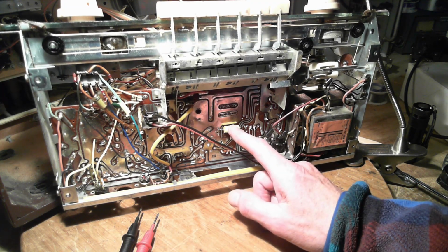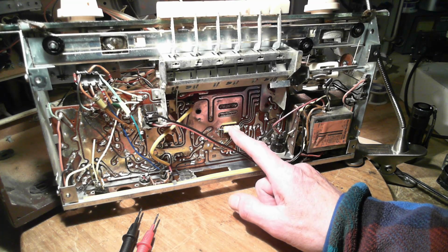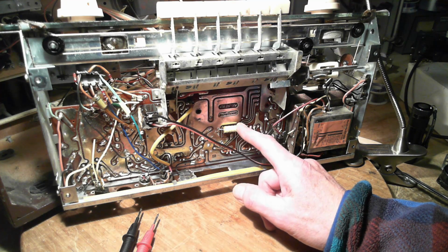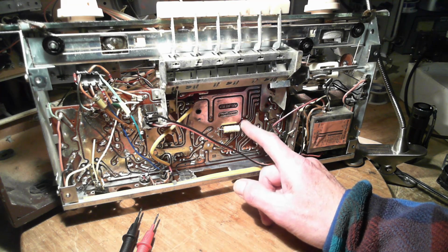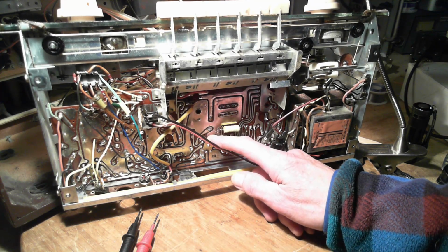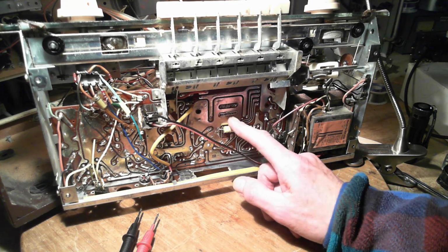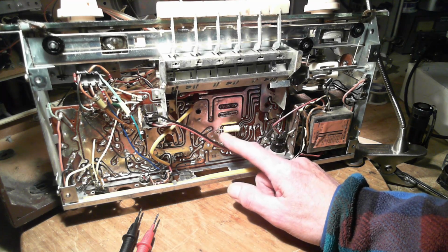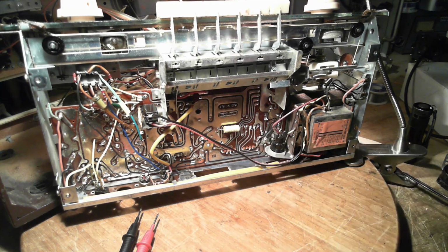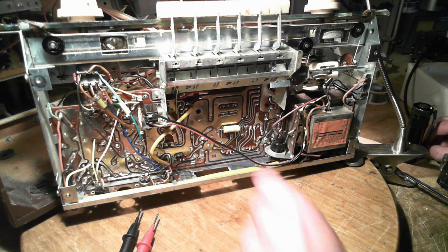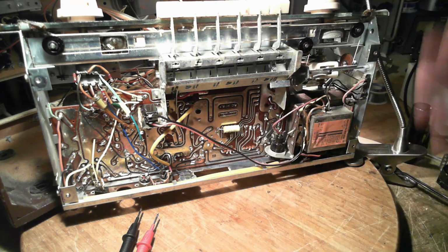The solution could be just turn this capacitor right around. Just turn it around, put it back in, and if my theory's correct, that would move the outside foil connection over to here on the ground, and so the outside foil would be grounded, and that would shield the capacitor from whatever's going on in this zigzaggy piece here. So that's what I'm going to do. I'm just going to flip it around the other way, see if that makes any difference. Don't really know what's going to happen. Bit of a long shot, but I haven't got much else here.